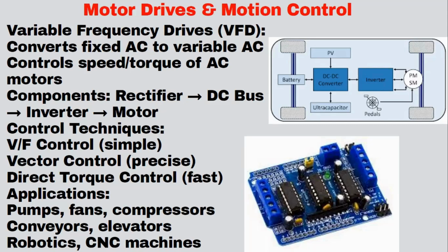For control techniques, V by F control is a simple technique. There is another technique, vector control, which is a very precise technique. Direct torque control is a fast technique. Applications, where do we use it? Pumps, fans, compressors, conveyors, belts, elevators, robotics, CNC machines. So these are the uses of your VFD.